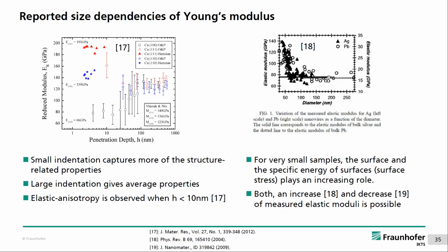And there are also some hints that on lead and so on, you get an increase in the Young's modulus. So not my measurements, these are reports from literature. I would check them carefully to see if it has nothing to do with the calibration and so on. Just to say that in nano-indentation you always have to check for size effects, because materials behave differently at small scales.